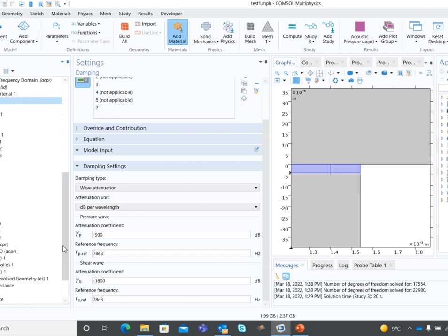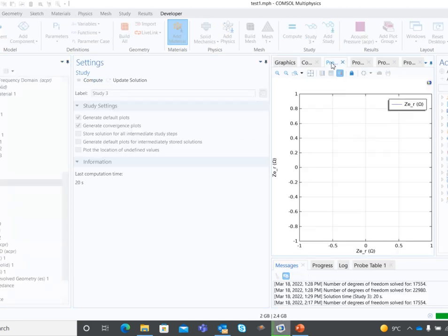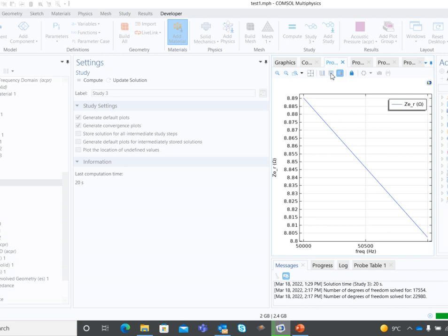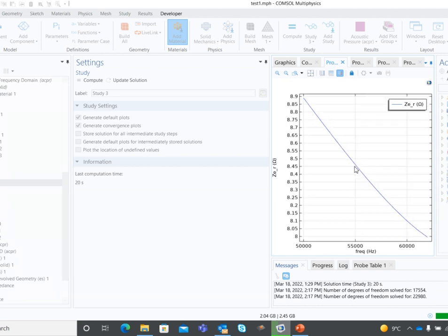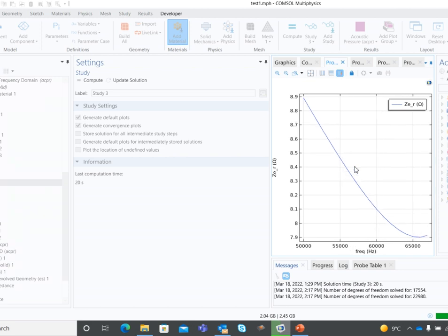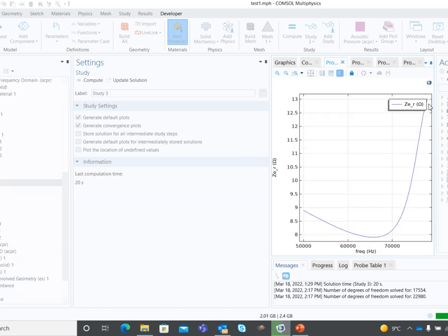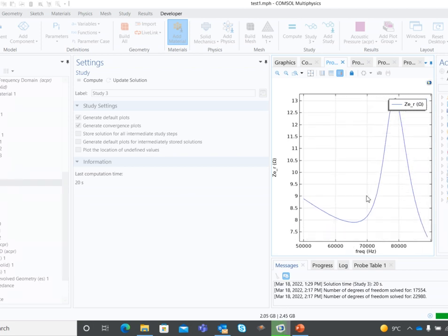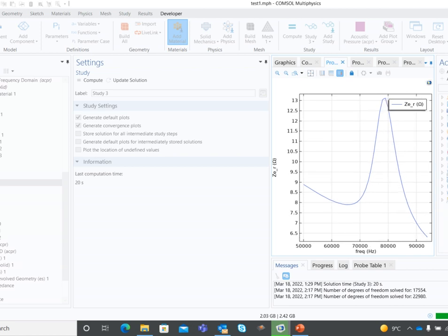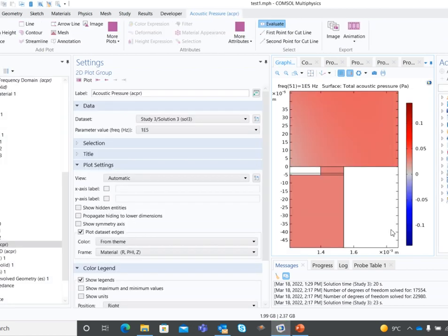So if you add those dampings and you simulate the response, you will start looking at the baselines in the real part of the simulated impedance, and this baseline is representative of the damping, because if I turn off those dampings, you don't have that baseline. You're going to again have a very high Q peak without any baseline. So this baseline in the measured impedance is because of the vibration in the backing.